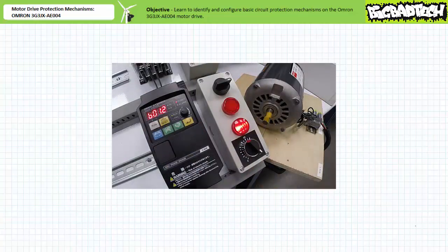As expected, when an operator presses run, the motor drive linearly increases applied voltage and excitation frequency over the acceleration period. Note the bottom pilot light is low side switched by multifunction digital output P1 executing the run function. The motor accelerates and speed stabilizes. Note the top pilot light is high side switched by the multifunction electromechanical relay output executing the constant speed arrival function.